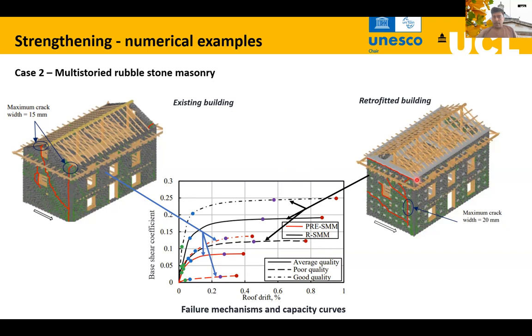Now, in the retrofitted case, those cracks are broken, as you also saw in the presentation by Juan Carlos. These 2 elements, and also the ring beams installed, have acted as a barrier for the complete full-length crack development. So we have more time, more deformation capacity, let's say, before collapse. And the complete vertical separation of the out-of-plane walls is also restricted. That is because of those ring beams and, of course, the improved cross wall connections provided by the strong back.